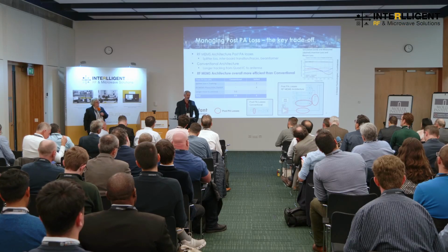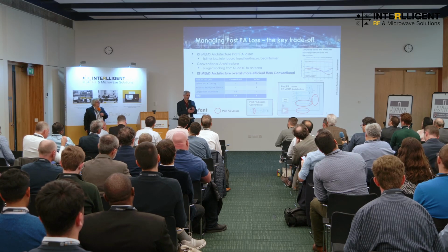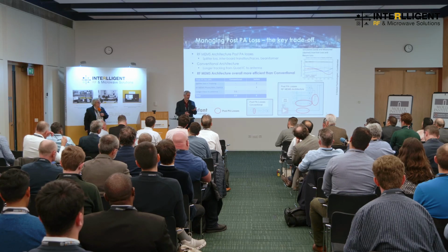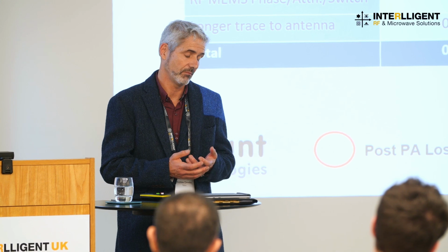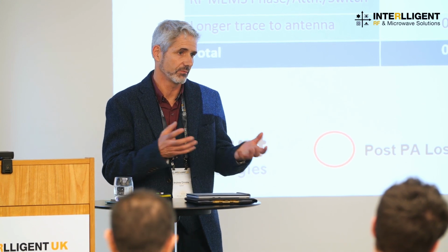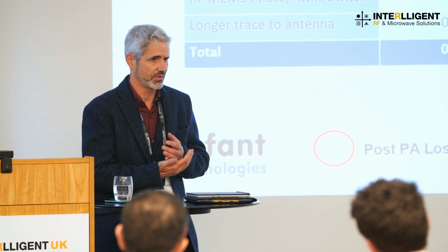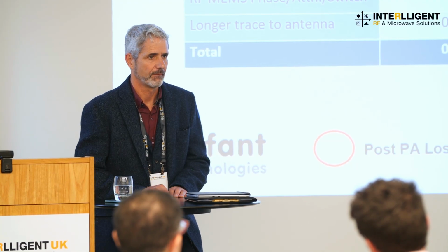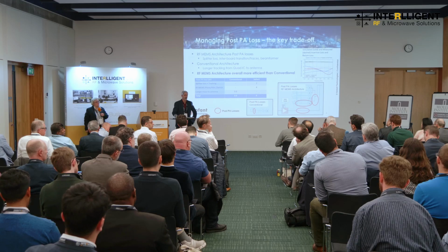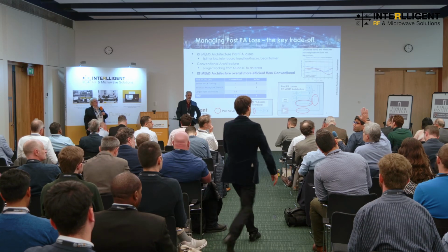You have an option. You could change the ratio. I mean, we set the ratio because it was a nice mix, a nice blend. But you're right. You could reduce the number. You could put one PA per 8 antenna elements, or you can play around with that number. We've set it on an architecture and scaled out designs and everything based on 1:16, but it's not fixed. I think this architecture from the DPD point of view is one of the best. I mean, you can do it easily in a phased array, which usually we cannot do. Yes. Okay. Thank you very much. Yep.